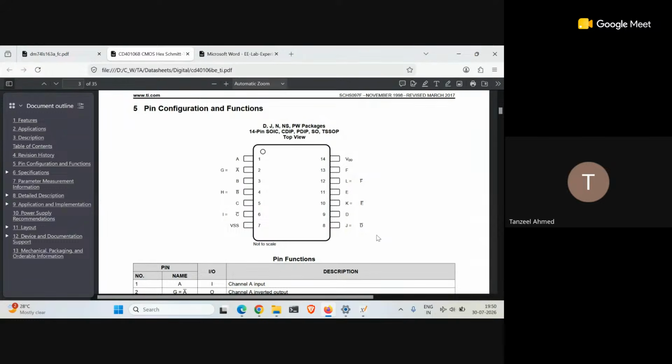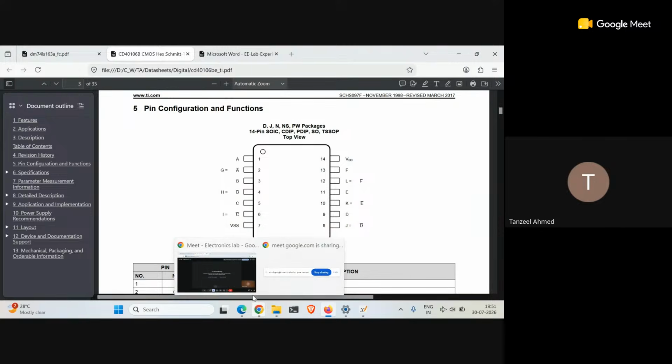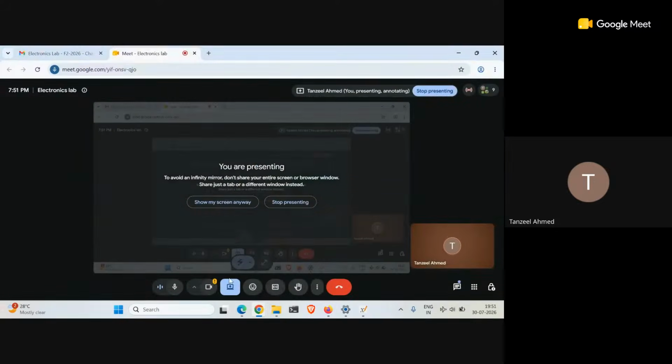And then, once you are done staging all your gates and your logic such that the 4 output pins are going from 4 ones to 4 zeros, you can record the output with the channel B oscilloscope, compare it with the clock signal and show that you have actually managed to achieve inverted counting from your 163 counter IC. So that is how you can complete experiment 3.